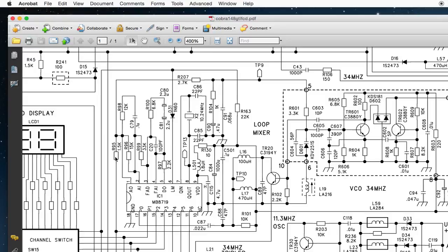Sometimes it's literally just a pull up or pull down. That's all it is. Sometimes it's not necessarily just that aspect. It's not necessarily just trying to get the phase detector to work harder. It's about actually controlling the voltage going in as well. So it might be you've got a phase detector which is putting mainly negative pulses out, and you need a positive pull up to balance it out so you get a voltage coming out as well. That's the other aspect too. It depends on the chip really, but generally there is some kind of biasing involved. So there's that resistor there, which is in that example diagram I showed you just now.